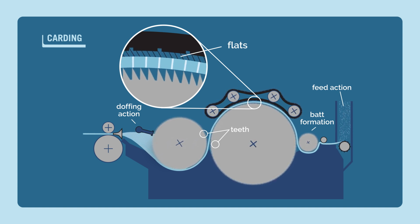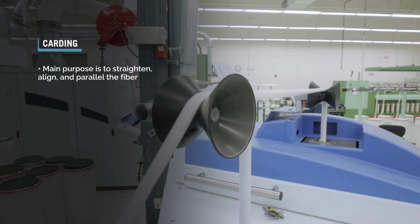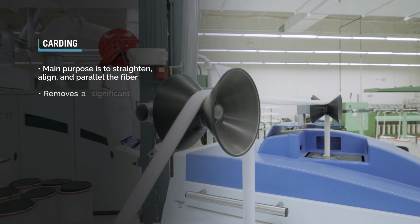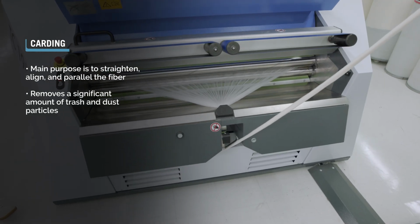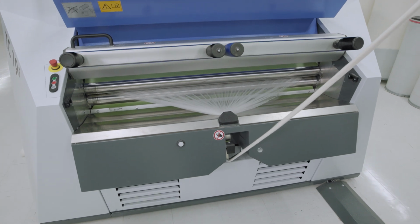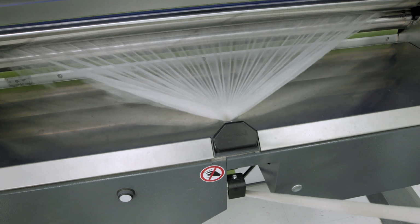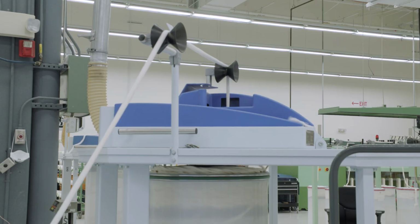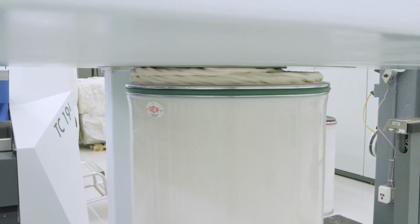The wire-wound cylinders acting against one another in conjunction with the flats are the actions that accomplish carding's main purpose, to straighten, align, and parallel the fiber. The card is also a very efficient cleaner and removes a significant amount of trash and dust particles as well. After the semi-aligned fiber is removed, doffed, from the last cylinder, it is condensed into a sliver using a trumpet, or funnel. The sliver is then coiled into a can for temporary storage and transport to the next process.